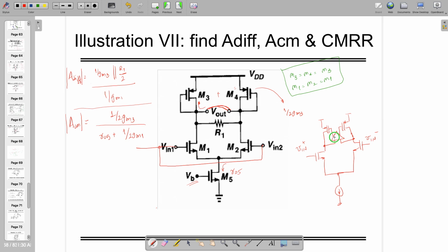let's assume that I am applying gain boosting to this A1. So in that case, in differential mode, you have to take the half-circuit approach. This is going to be 0, and in between this transistor A1 there will be ground, and you have to consider that, right?